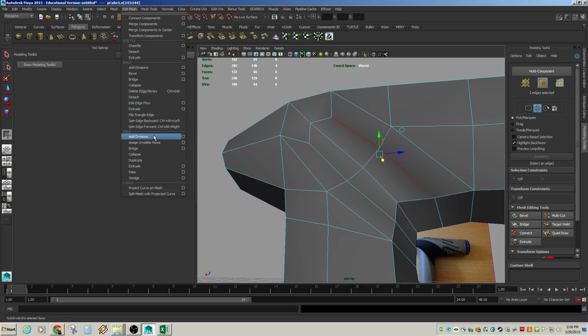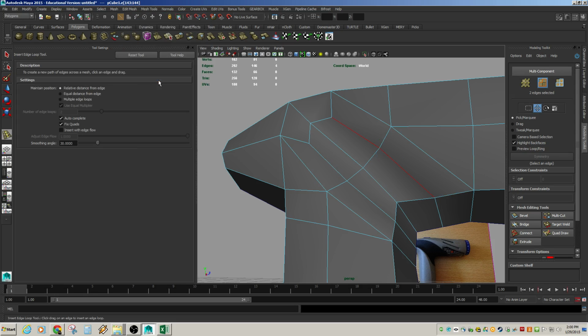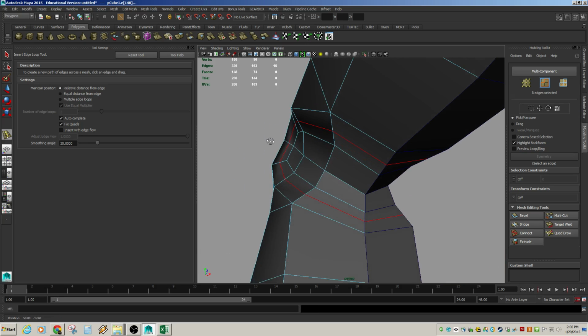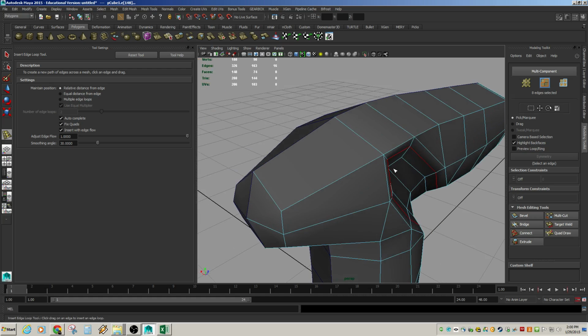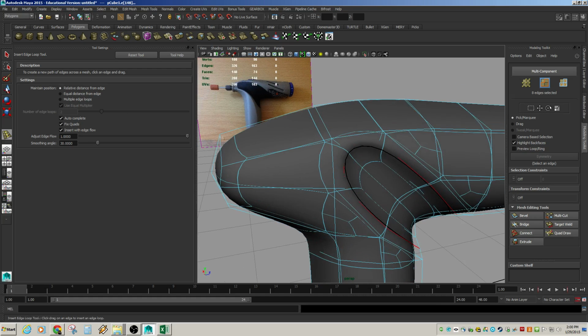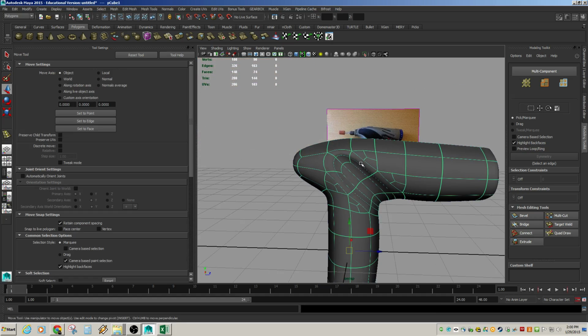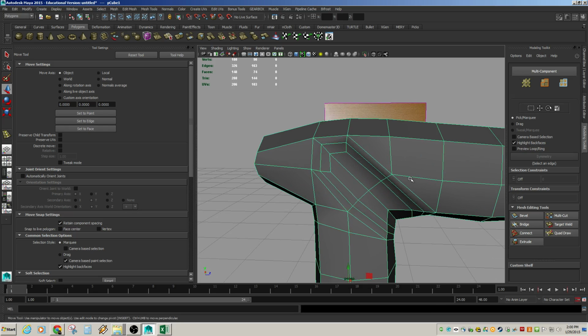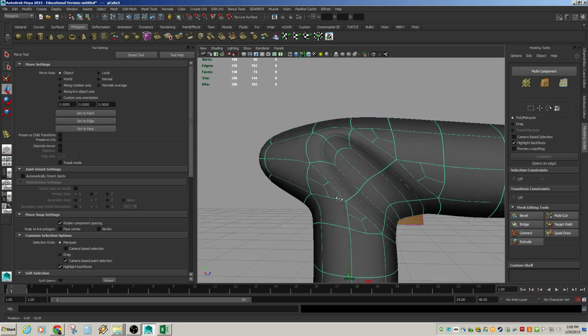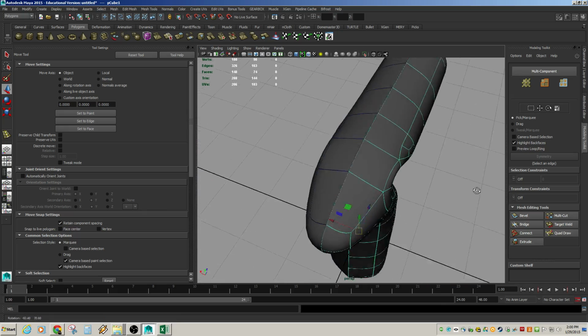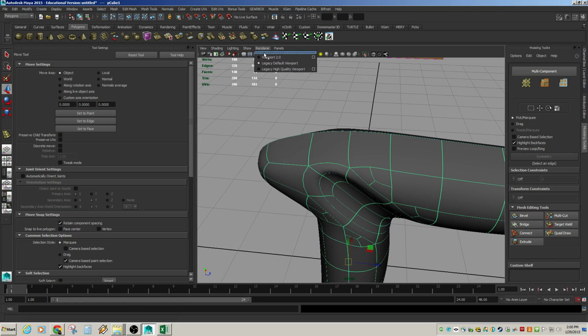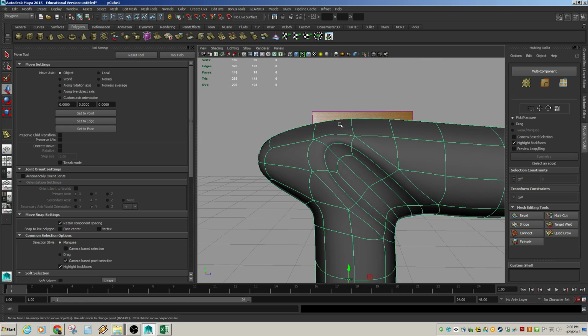And so if I go to Edit Mesh, I'm sorry, I keep doing that. Insert Mesh Tools and Insert Edge Loop, you'll see that's going to go all the way around through there, right? And we get some pretty nice options there, especially if we're using the Insert with Flow, right? So it's going to keep that pretty decent, right? So that's a little more of what we need. I don't know why it's subdividing that like that. That's what it really should look like.